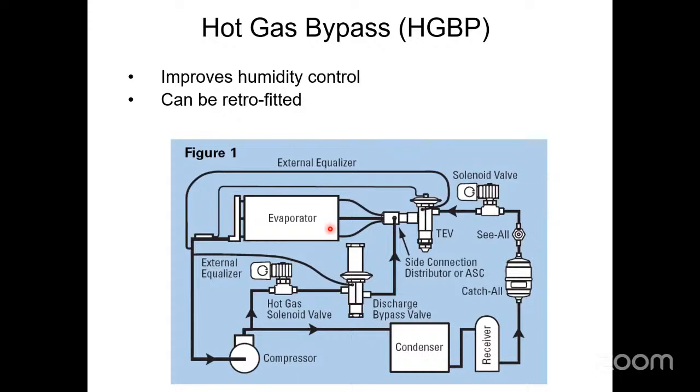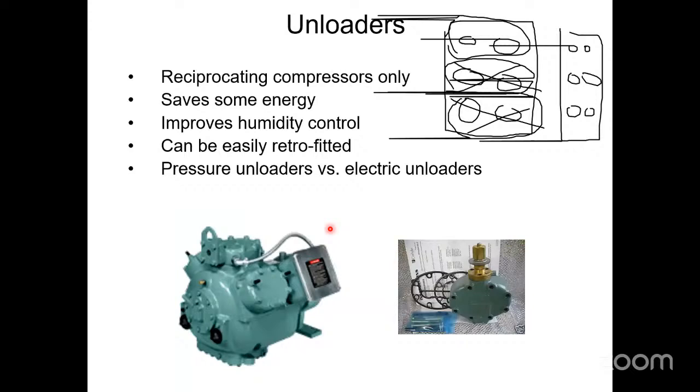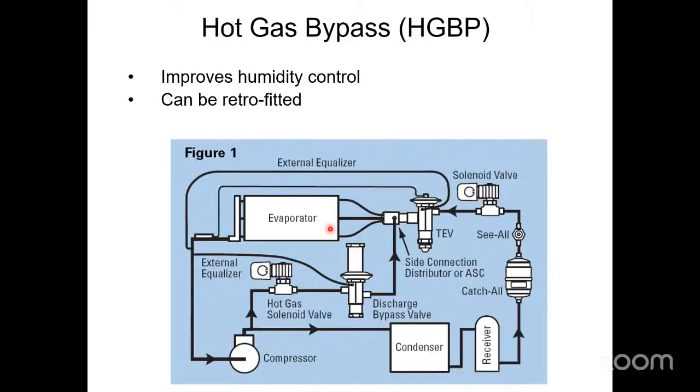Specifically, where you're allowed to use it is going to be on the first of many stages of compression. So let's say you don't have recips. You can't do any of that unloader stuff that I was talking about. That wonderful drawing can't be done. You got scroll compressors on a more modern machine, and you can't get the four bare minimum stages. You can only get three because you only need 20 tons of VAV or whatever it is, and it only comes in a three compressorized machine.